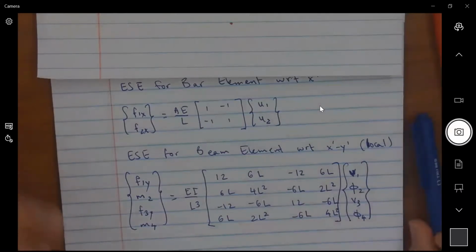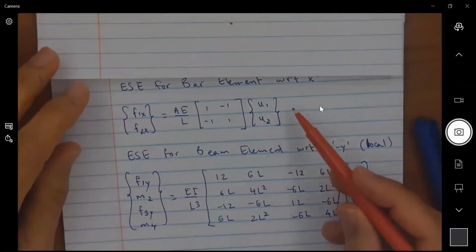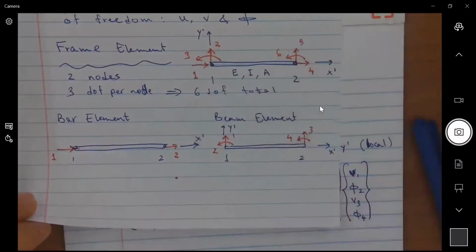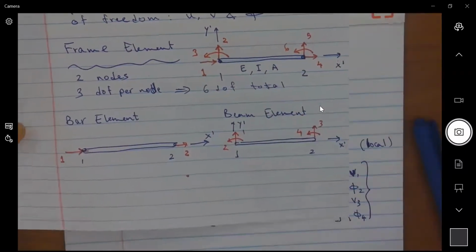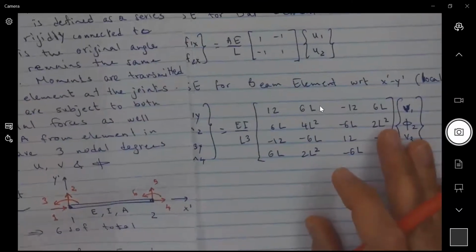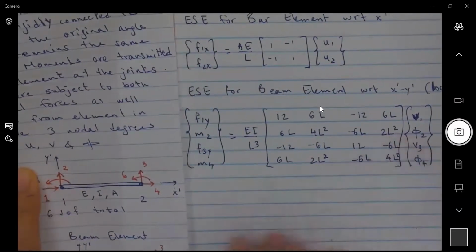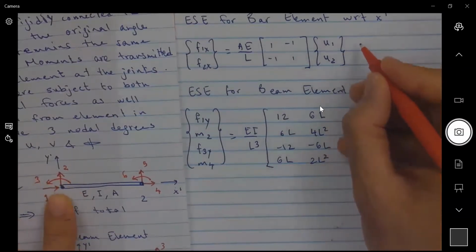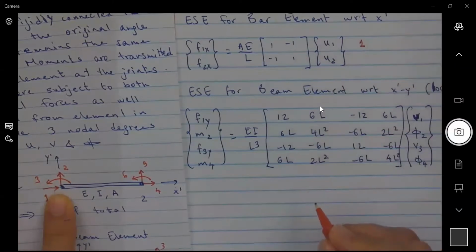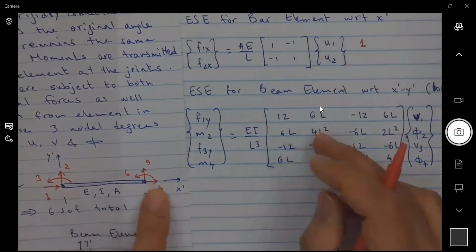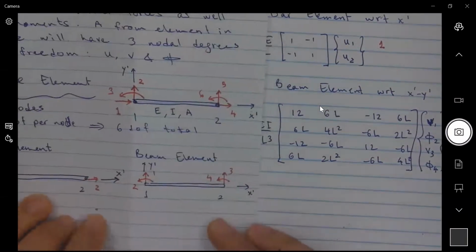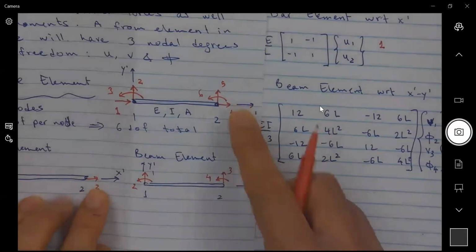Okay. So what I'm going to do now is write the corresponding frame degree of freedom next to each of these equations. So I'm going to come here and I'm looking at my frame element. And even though I call this 1, here it is also 1. So I have here 1, degree of freedom 1. And 2 would correspond to 4. So you see 2 and 4 corresponding to each other. So I'm going to put 4.